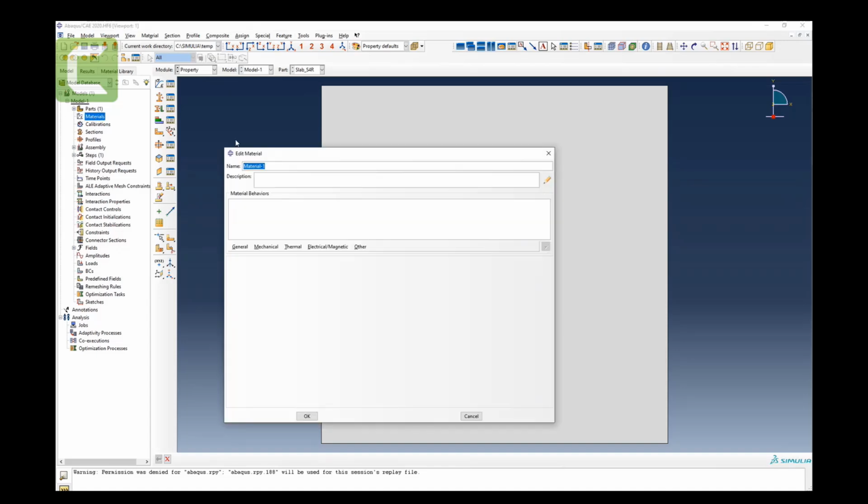So let's click on materials, and let's say we put steel, it is a steel plate. Again, these names, you can put any names. Your answer will not be affected by what names you put. You can put material one, or material-steel. Again, it does not like it if you put a space. Material steel with a space, no, it will not like it. What you need to do is put an underscore or dash, then you can put steel, or you can put a continuous name like this. It's up to you, the way you like it.